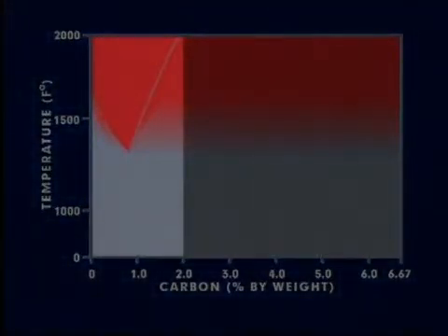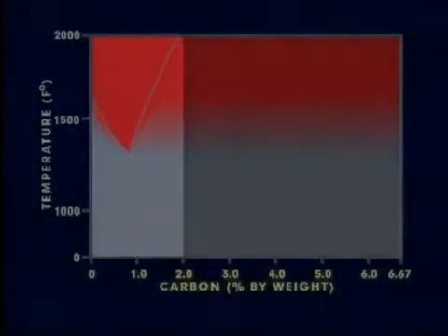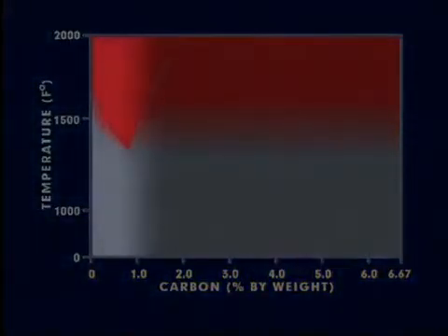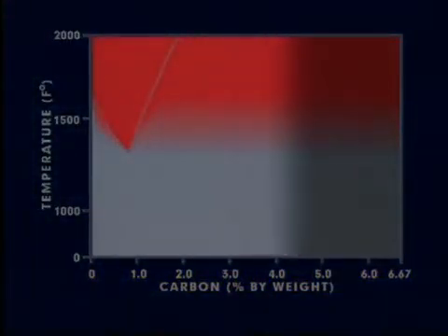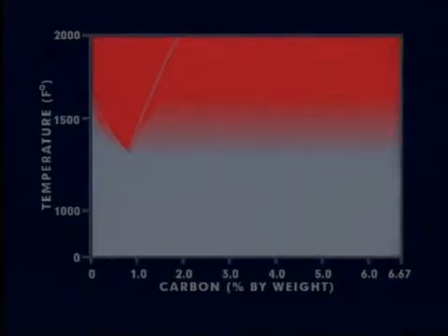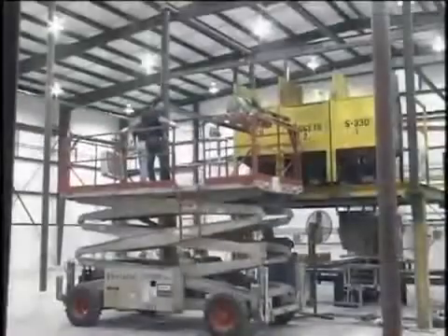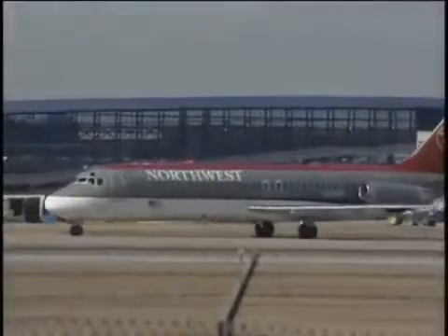less than 2.0% carbon. The carbon content is the major factor in determining the properties that can be developed in steel. The use of very low carbon contents or very high carbon contents provides many different steel compositions with very different properties. For this reason, steel is suited to a wide range of engineering applications.